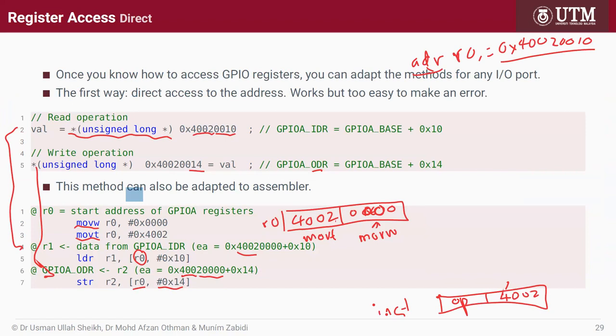So if you do STR to a register which is not configured, of course nothing happens. So to turn on the LED on your blinker, you have to make sure it's in output mode first. Then you can blink. By default it is input.